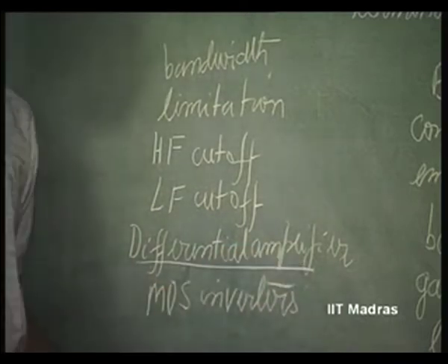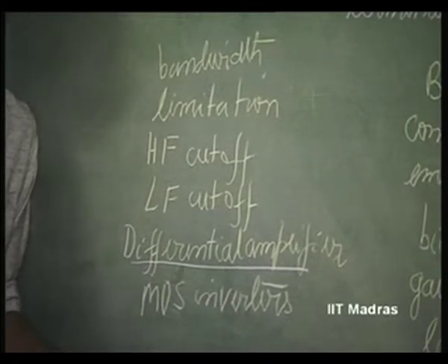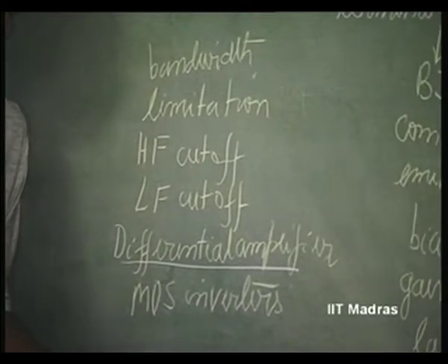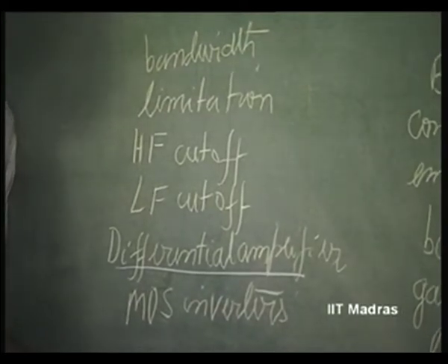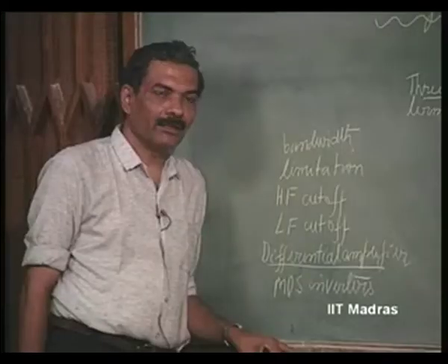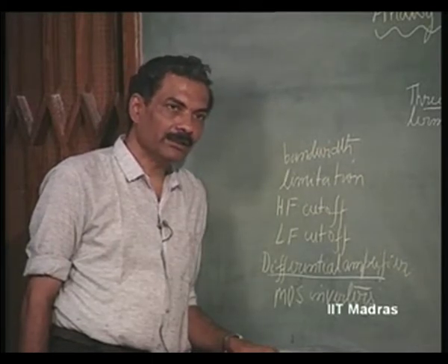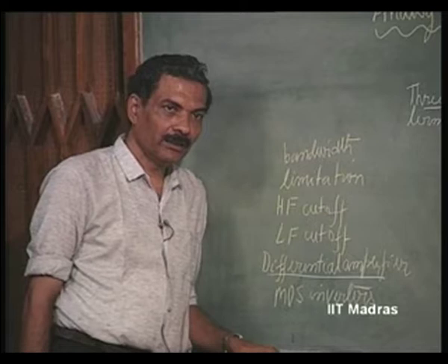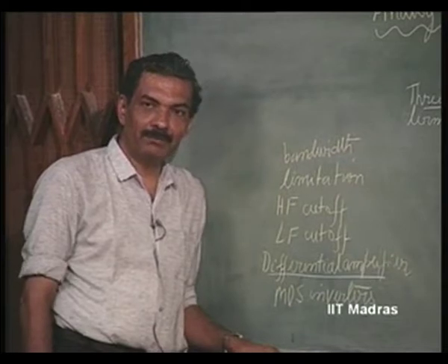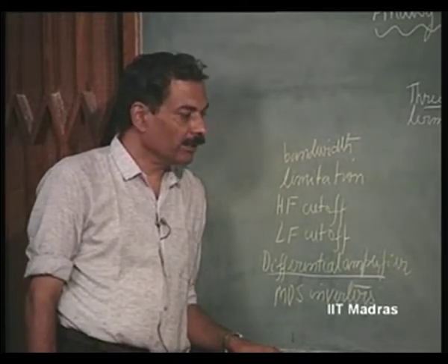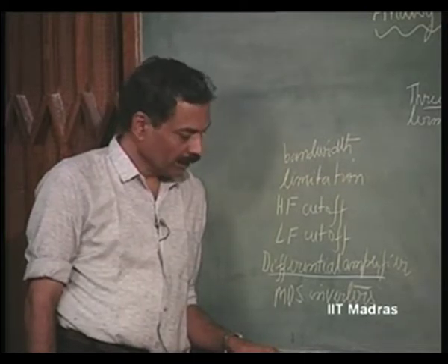So we said how this facilitates getting rid of bypass capacitors, and how using dual supplies we can also get rid of the input coupling capacitor, and how by direct coupling we can get rid of the coupling capacitor from stage to stage. What are the disadvantages associated with direct coupling? What sort of signal limitation will occur when NPN transistors alone are used? How the NPN-PNP combination helps us in avoiding what are called level shifters.